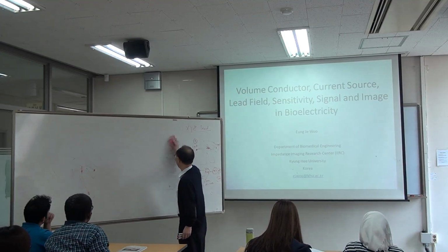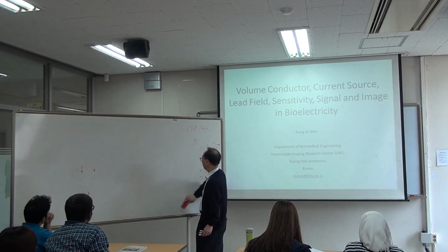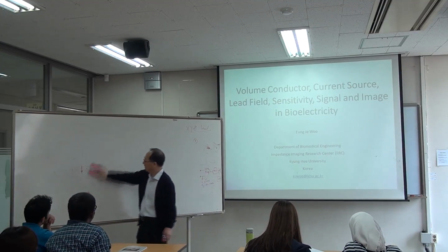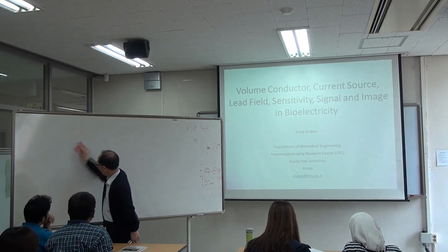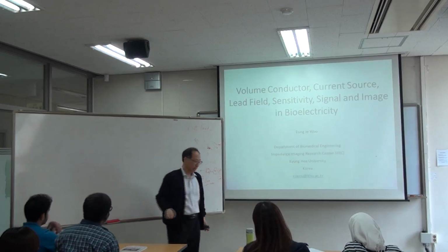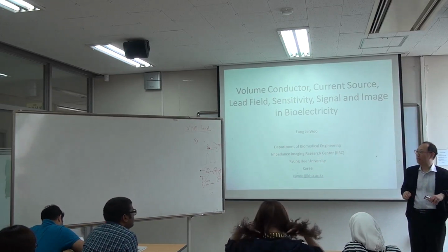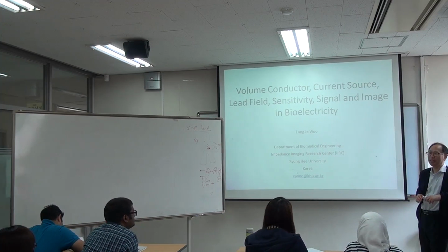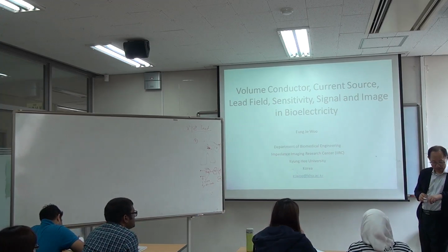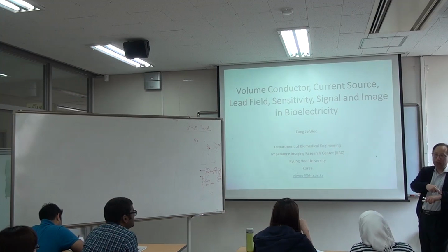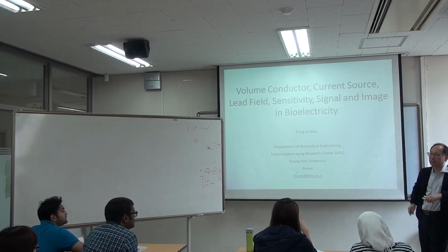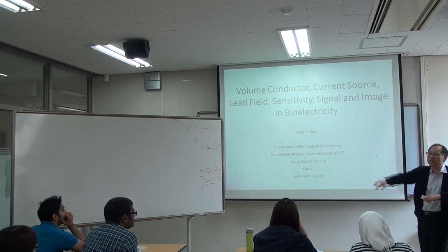Okay. Now let's think about the impedance measurement case. The people who are working on mobile health devices try to measure heart rate on a band or watch. They quickly realize that if they attach two electrodes here or in any direction, they are not measuring any ECG signal, because of this.